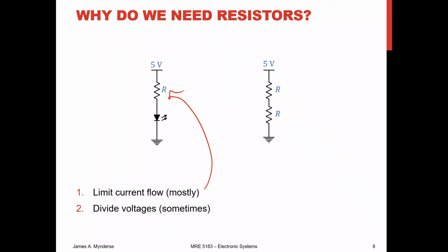Is there too much? Is there too little? There's always going to be a spec sheet for your LED that's going to tell you what the maximum power dissipation is. So that'll give you an upper bound, and the lower bound is going to be based on visibility.